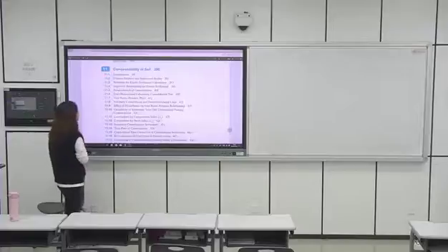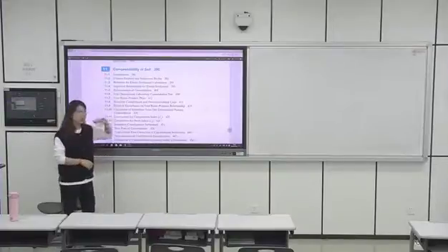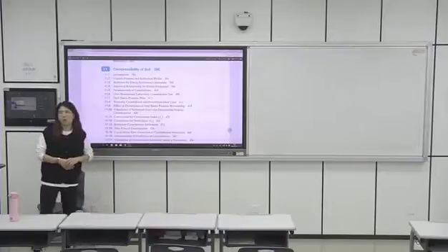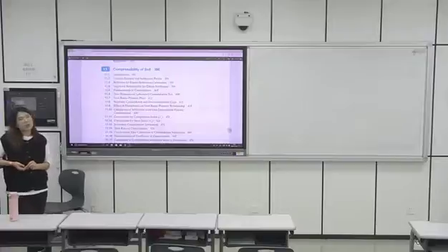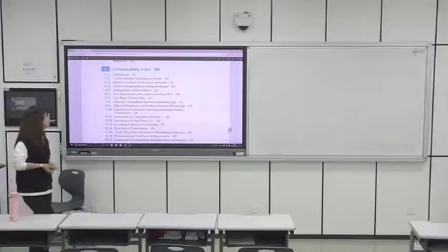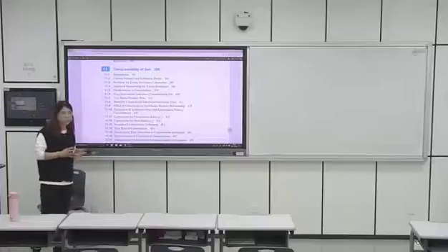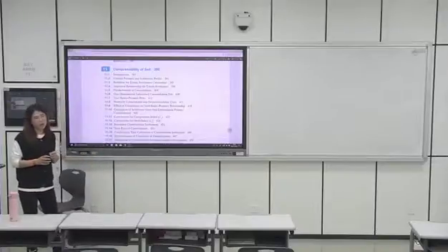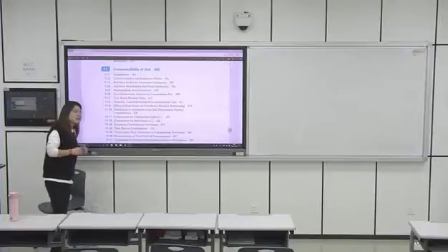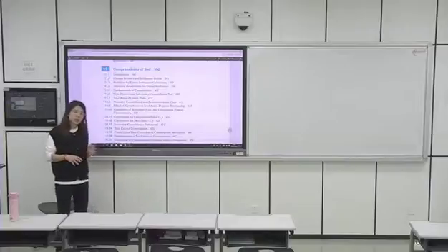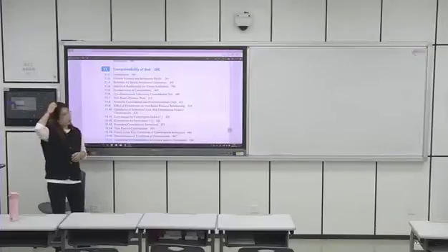And then the main thing here is the fundamentals of consolidation. What is consolidation, right? Remember that we explained the consolidation with what? With a spring cylinder model, right? The spring cylinder model helps us to understand the consolidation process. Actually, it is a transition between effective stress and water pressure. But the total pressure is kept constant during consolidation, right? During consolidation, because water is squeezed out, the soil shrinks, right?